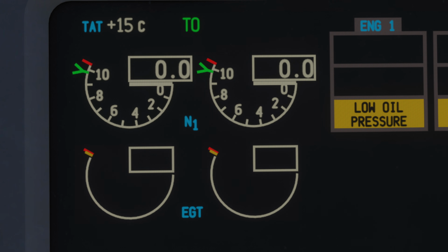Now, this directly relates to all other stages in the engine, because even if the temperature in the combustion chamber may be 1000 something degrees and the EGT shows you 600, if the EGT goes to 700, the temperature in the combustion chamber rises in a certain relation. So EGT, made simple, is a temperature reading taken somewhere in the engine, and then limits are defined depending on that stage in the engine, but they apply to pretty much the entire engine.